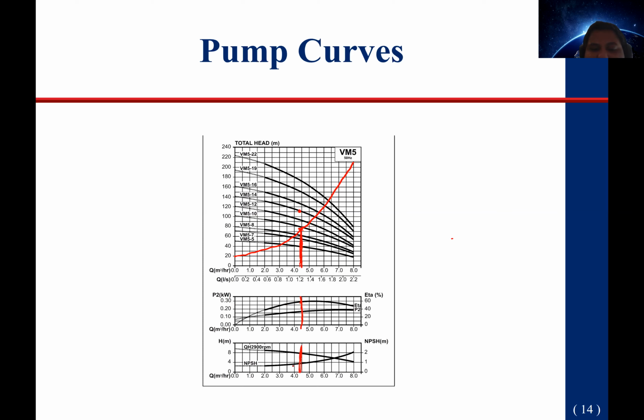And one thing you'll see here is the curve on the bottom is the suction head required, and the top curve is the suction head available. Usually beyond this point, this is unfeasible. So this typically tells you that the far end of your pump curves you're not going to want to operate at, because then you have issues with cavitation. And so you have a homework question or two that deals with looking at pump curves.